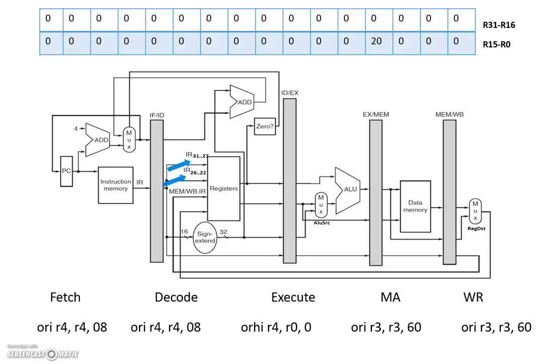The previous instruction ORI will be passed on to the next stage till the write back stage. The instruction at the write back stage matches that of the fetch stage. Now in this stage, ORI will be passed on to the decode stage, and the new instruction LDW R4, R0, R4 is accepted.